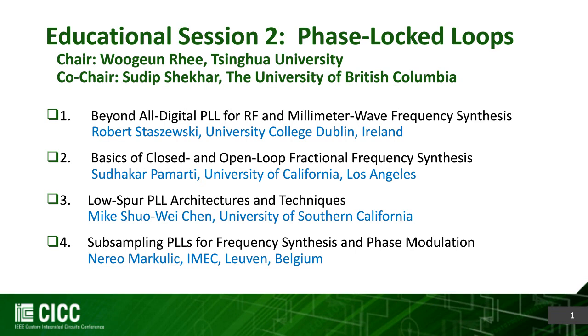Yes, so it certainly takes power and area for those spur cancellation. For example, if you remember, I showed the first prototype for the single tone cancellation. That one, by far, in our experience, is probably the most power hungry and also area hungry technique. The reason is because we actually synthesize the digital sine wave, and also because we were experimenting with ideas, so we over-designed quite a bit. Among all the spur cancellation, those are probably the most costly ones.